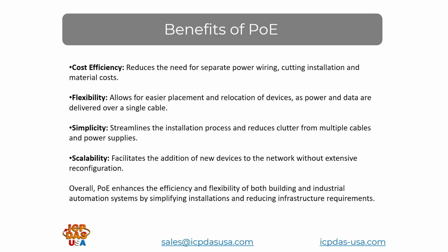Flexibility. PoE can be added to a standard existing Ethernet network just by adding some PoE switches, which can share the communication from the existing network or add on top of that, or it can simply be implemented separately by adding a second set of Ethernet cabling or using other standard Ethernet products. And then when you need to power a PoE device, you just simply use a PoE injector or a PoE switch at that point. PoE can be incorporated into standard Ethernet networks.